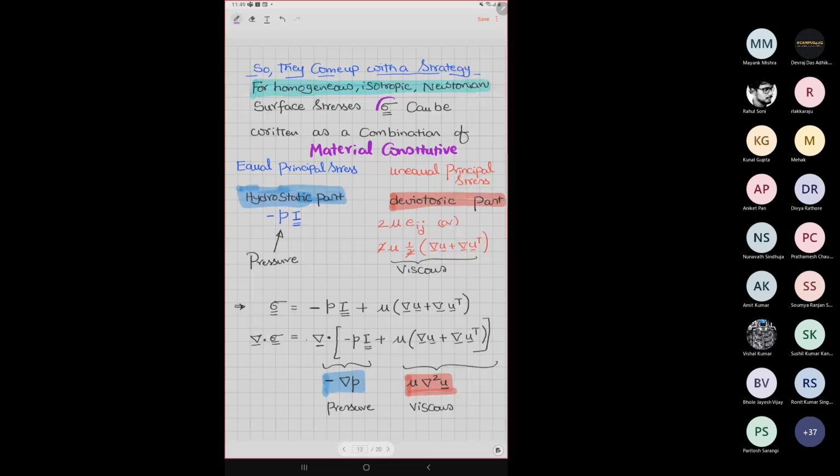There is no problem. But the easiest thing for me to realize is, whether it is a fluid material or an air balloon, or a piece of chalk, any kind of thing that can undergo deformation, breakup, and so on, can I really compress it equally in all directions? If that kind of force exists, we will call that one pressure. Basically, the stress component, or usually people call that the hydrostatic part.